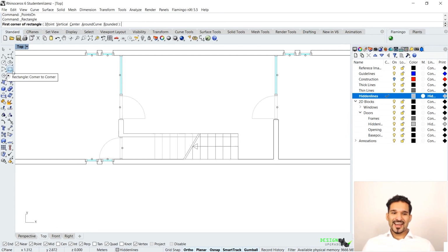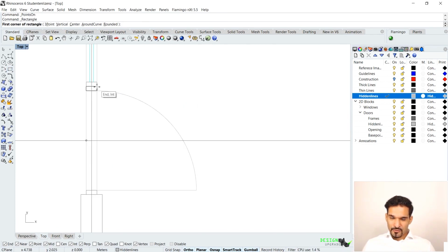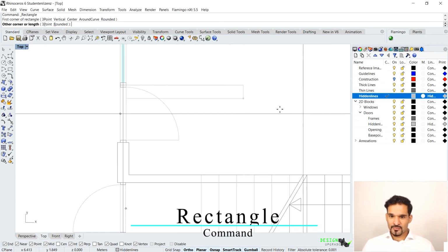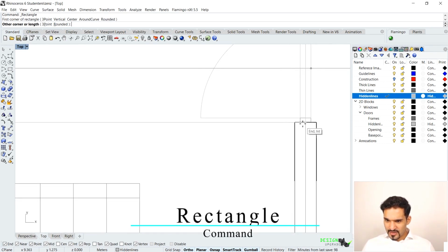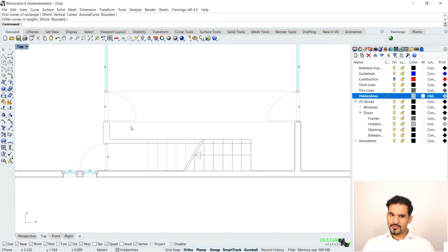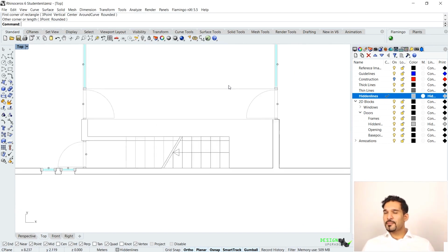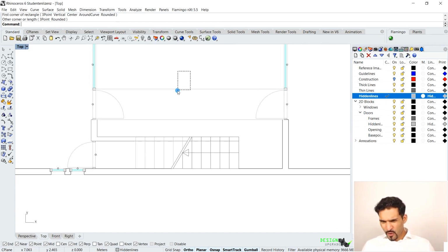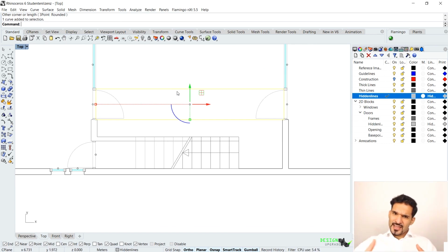Now it's actually quite nicely done by Tadao Ando, I have to say. The bridge is exactly the frame size that we have drawn for our doors, so I can literally just draw a rectangle without any other feature, from frame to frame. That is more or less the basic concept of that bridge. Now we also have on the sides that balustrade which is made of concrete, so we have to give an offset to that of 15 centimeters.